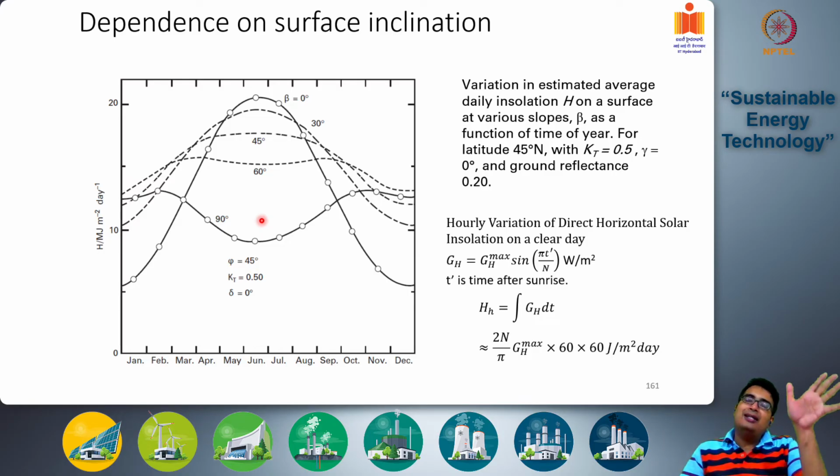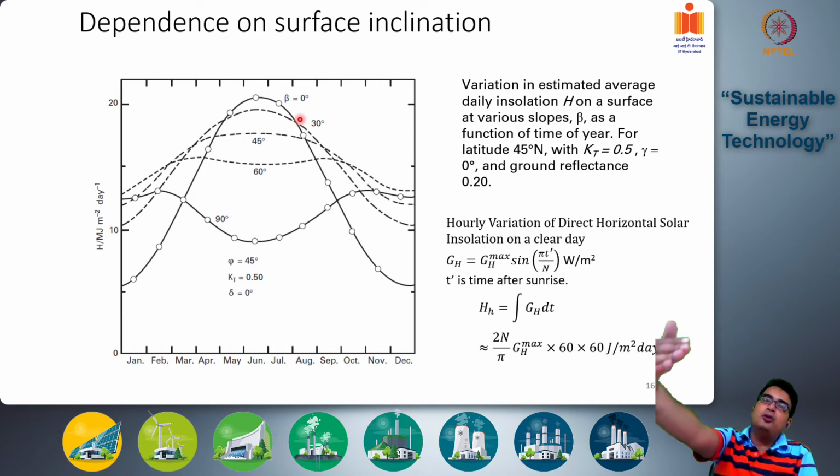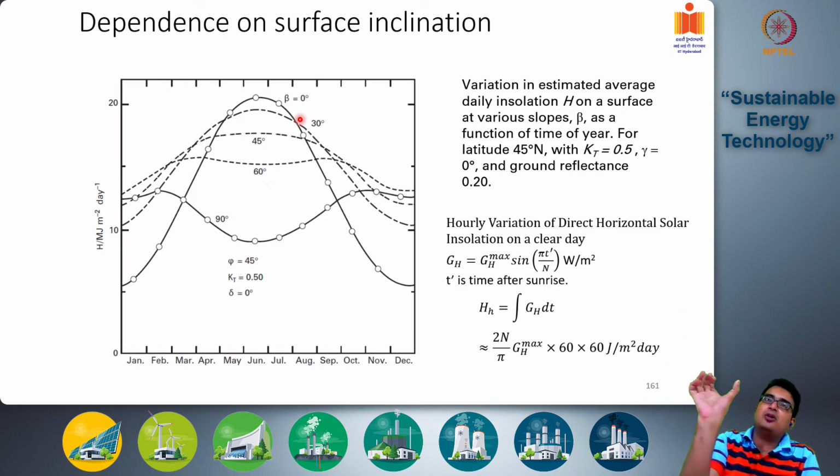Okay. So a 90 degree collector is going to collect more of the sunlight in winter times because it is seeing the sun more often than in the summer times when the sun is directly overhead. So the angle of inclination is usually much larger. Whereas it's the opposite case for a ground collector, because in winter the sun is low on the horizon, the theta value is much larger. So in G cos theta, the cos theta value decreases. So you have a large discrepancy in the winter versus summer.